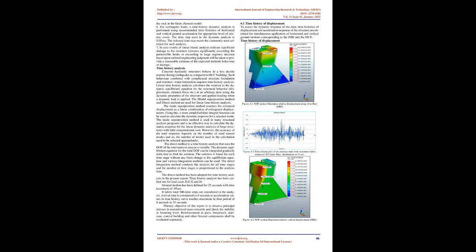U/S hydrostatic loads. A linear distribution of pressure variation has been considered. The hydrostatic pressure is maximum at the base of the structure and gradually reduces to zero at the FRL/MWL. Hydrostatic force on upstream face, maximum reservoir level, FRL, equals L1267 m. Minimum elevation of base equals L1218 m. Depth of water, Y, equals 1267 minus 1218 equals 49 m. Maximum pressure ordinate at upstream face equals 10 x 49 equals 490 kN per square meter.